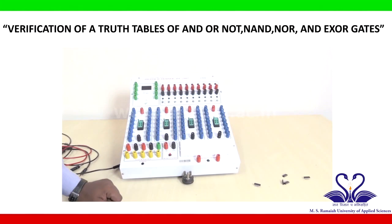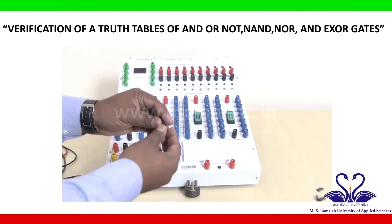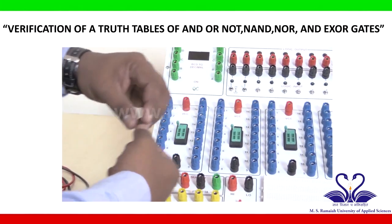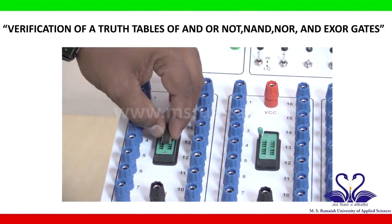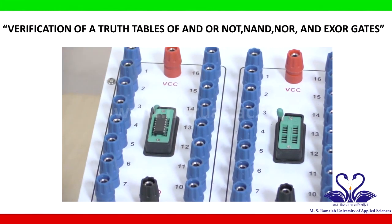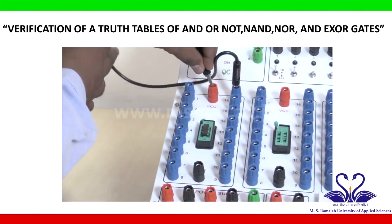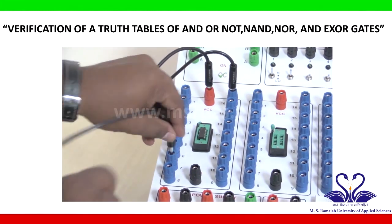Now I will verify the truth table of a NOT gate. NOT gate IC number is 7404. I will take a 7404 IC. So notch, this is notch, pin number 1. I will mount it on the IC trainer kit and lock it. Pin number 14 is VCC, so we'll connect here. Pin number 7 is ground.